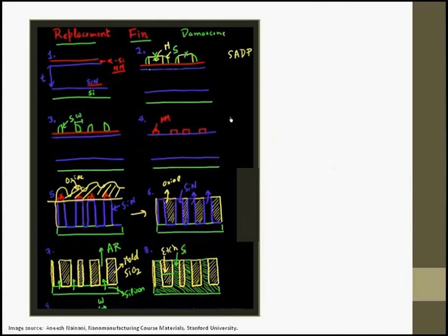And we start with the litho patterning, which of course needs to create a nice pattern for transfer to etch. But one thing that's interesting about this flow now, as we go and perform double and even going forward we may see quadruple patterning, is with each subsequent etch transfer to a new hard mask layer, we can introduce errors in the line that get propagated and made worse in subsequent etch steps.